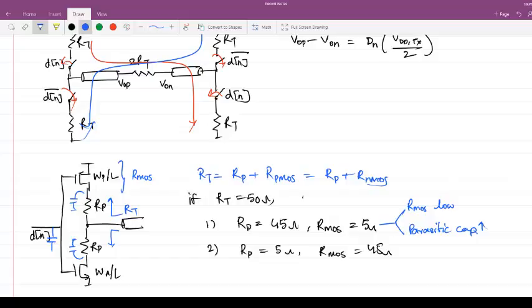And this parasitic capacitance is more of a problem because it will give you data dependent jitter at the output. So consider when you are always transmitting 1, let me call this CP up and this one CP down, right?